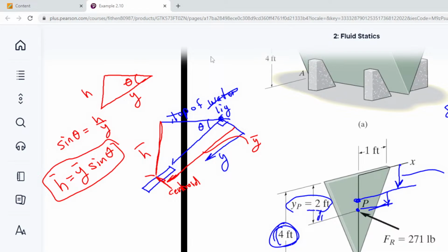Likewise, you can look at h bar, that's one specific location, but the triangular plate is located perfectly vertical. So here's your triangular plate. From the side view, from someone standing here, looking that way, they see this. You take the line and you cross it. You take a perpendicular. This is y. And guess what? This is h. So in fact, h and y are the same thing here. If theta is equal to 90, and it is, then h is equal to y. So in this particular case, h is equal to y.